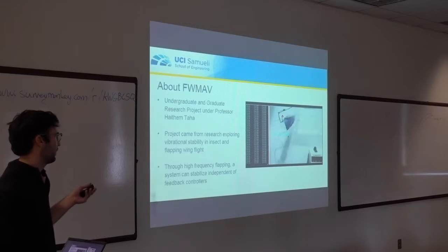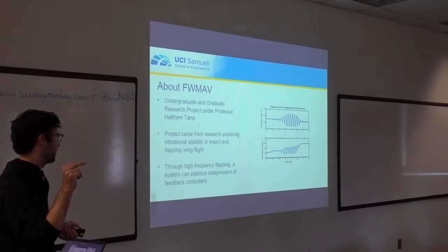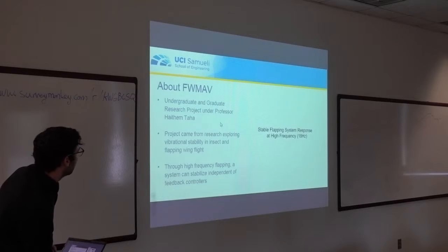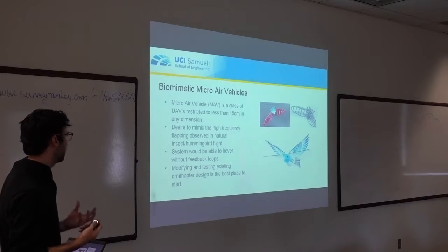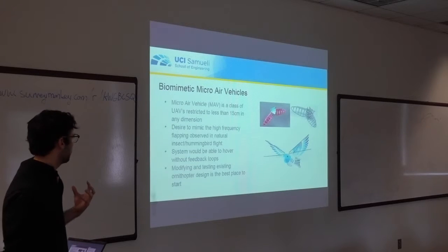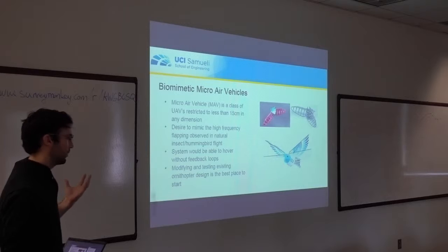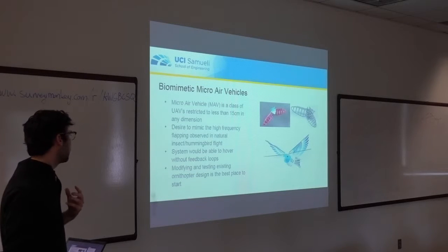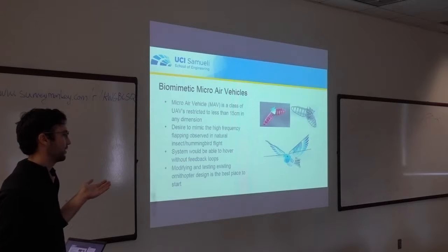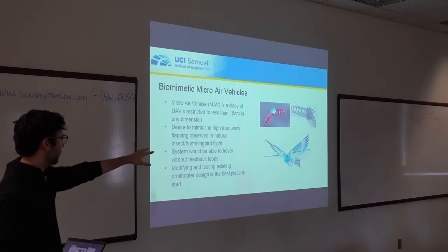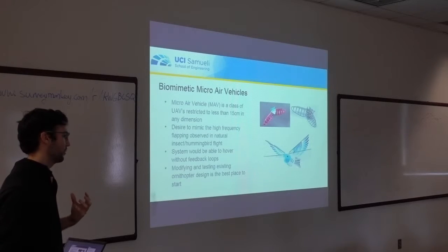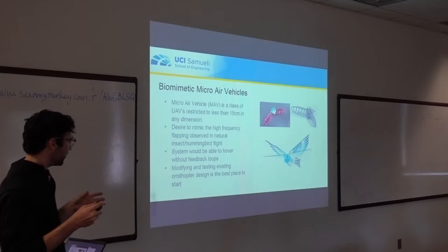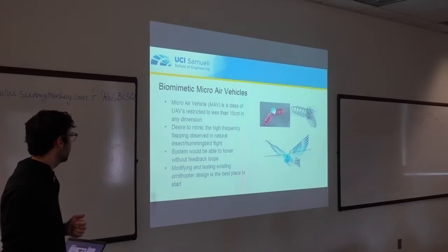So as the system starts to diverge, by increasing the flapping frequency, it stabilizes itself. So some of the possible merits to this are in biomimetic micro air vehicles. So vehicles that could stabilize independent of flight controllers. So that was the original purpose behind the Flapping MAV project. So we started by modifying an existing ornithopter design, so these toy birds that you see, and the goal is to produce the vibrational stability in a system that can operate independently of flight controllers.